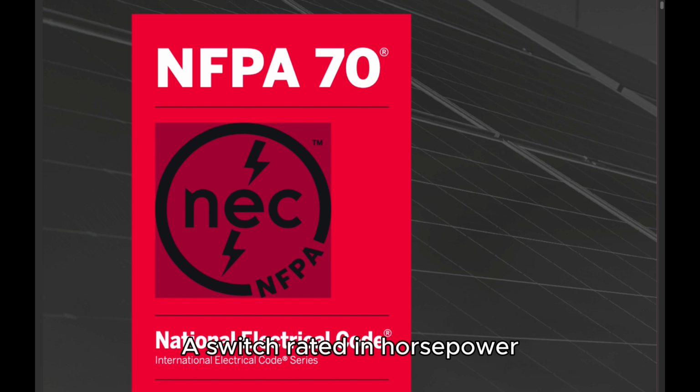A switch rated in horsepower that is capable of interrupting the maximum operating overload current of a motor of the same horsepower rating as the switch at the rated voltage. CMP11 switch, transfer. An automatic or non-automatic device for transferring one or more load conductor connections from one power source to another. CMP13 switchboard. A large single panel, frame, or assembly of panels on which are mounted on the face,